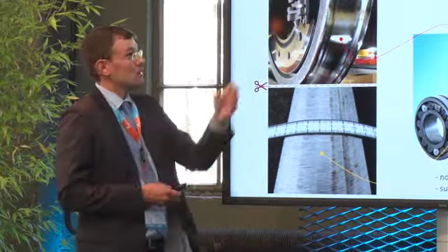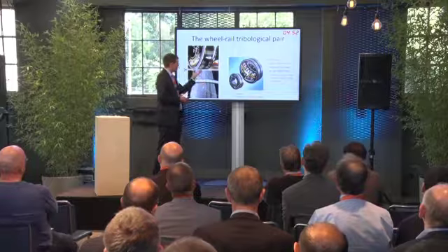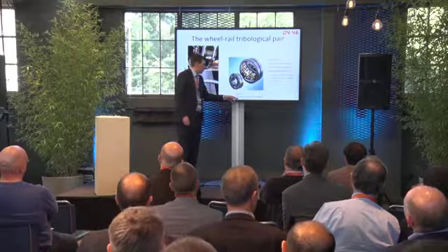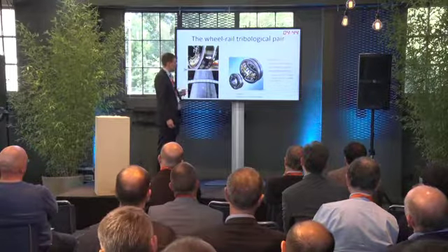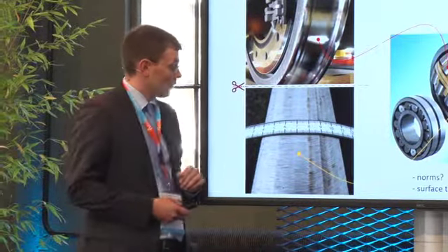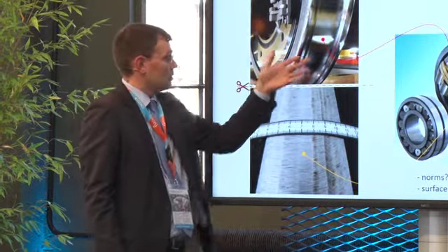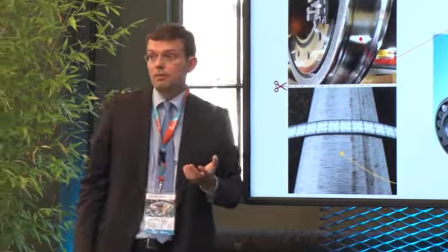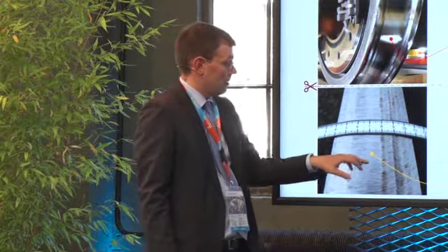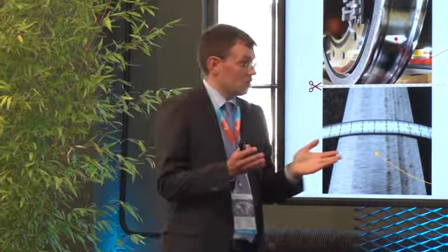So if we look at it as a tribological pair, we should compare the surface conditions at both sides. And also, for example, look at norms at both sides, the ways that the surface is being treated at both sides. Well, I didn't put here the norms, but if you look at these norms, well, they are completely different. It's like 2 different worlds. If you look to the treatment method, well, I think most of the wheels, all of us know, they are being reprofiled by turning. So you always have a milled surface here. And in most of the cases you have a ground surface at the other side. So does that match somehow or does it not match?